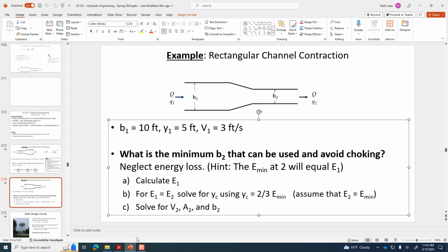And if we know the velocity is 10.5 feet per second, and we know the flow rate overall in the upstream location, we had a depth of 5, a width of 10, and a velocity of 3. So what is the overall volumetric flow rate? I wish I had a bigger whiteboard. Let me erase this stuff at the top here to give myself some extra room.